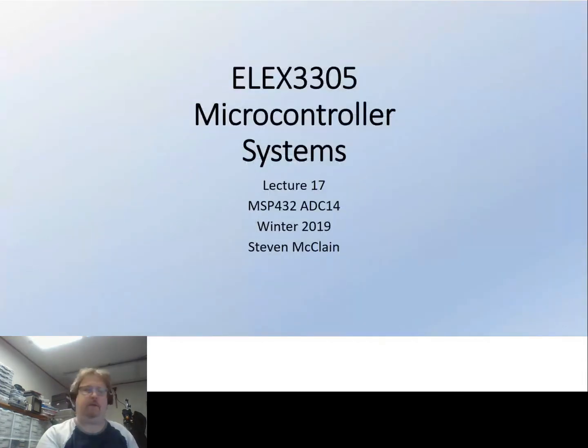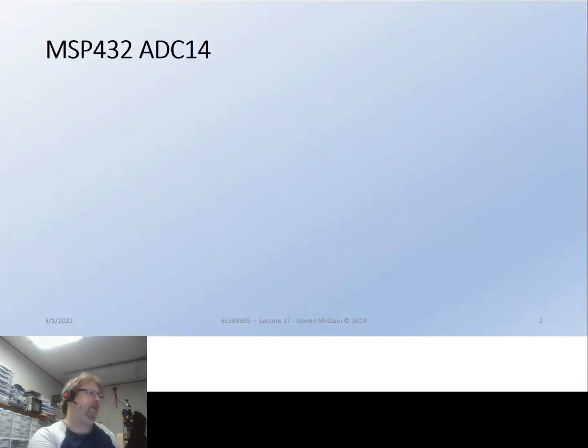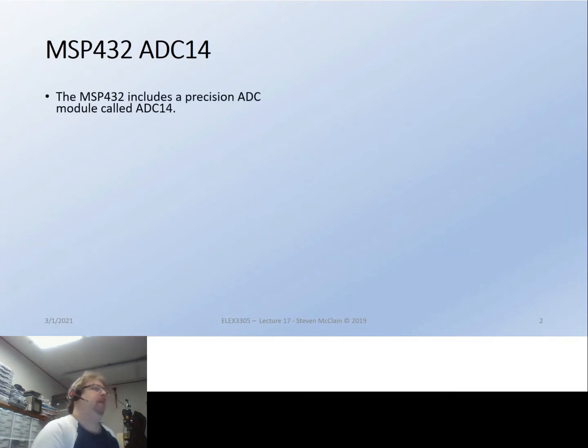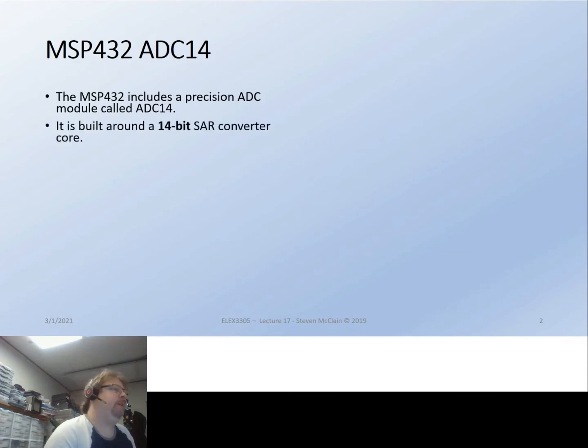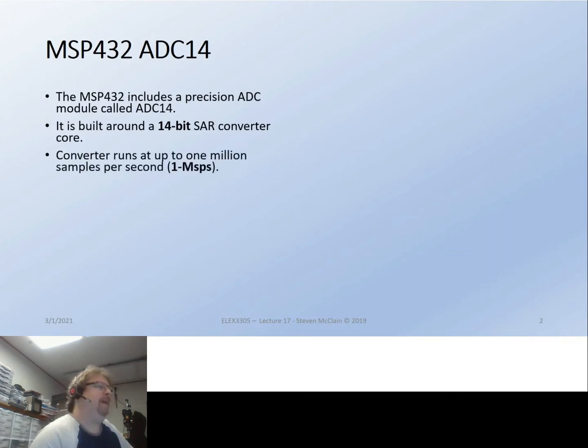Okay, it's more just setting of the registers now. Okay, well that's this one. There we go. Oh boy, the MSP432, which I really do like, ADC14 and everything. Precision ADC14. 14-bit SAR. You can get up to a mega sample. How does that time work again? So 1 million samples in a second? You betcha. Okay, 1 million samples.